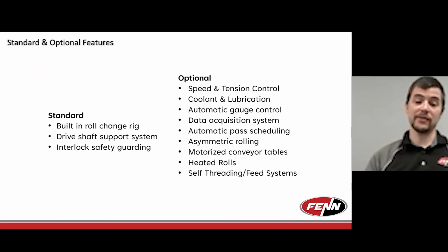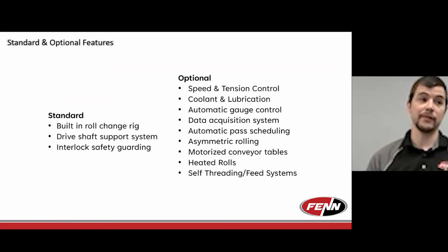The next step beyond that is us physically heating the rolls. Now, there are limitations on how much you can heat the rolls, and depending on the size of the rolls, it can add a lot of complexity. But there are two ways we can heat the rolls: either internally through a cartridge heater or externally using inductors. The idea of heating the rolls themselves allows us to basically apply a direct heat source to the material,